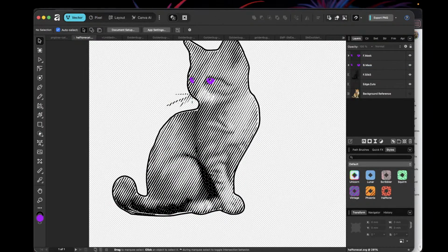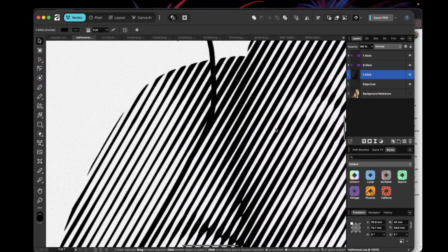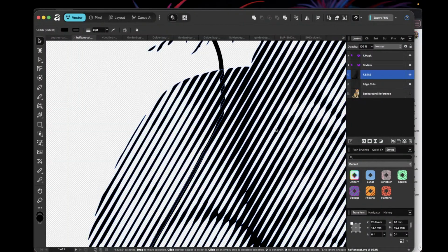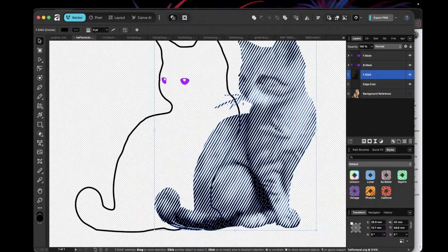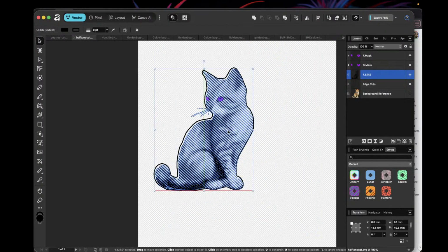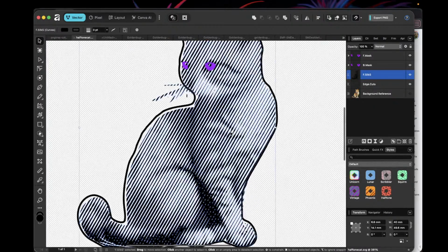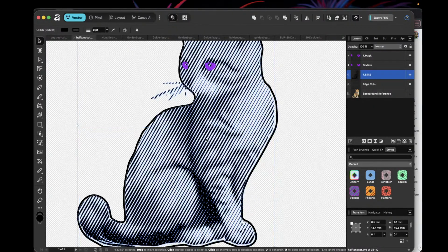But I like doing this because then I can import that halftone look as a top silkscreen layer, and it will retain all of that detail, because the silkscreen layer, when you're doing a traditional PCB, can't do gradients. It's just all there or not. It's typically opaque. And so by using different halftone effects or a newsprint effect, you can emulate depth with it. So it looks like it has depth, but it's just a solid black and white color.